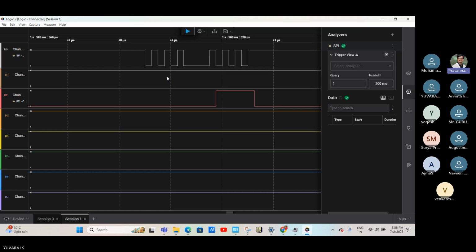Okay, but this is how we'll be transferring the data as well as receiving the data. Okay, if you have another board, you can connect this MOSI to MISO of that board and MISO to MOSI of this board. And apart from this, you just need to make one digital pin as a logical 0 for the slave select. Okay, so make that as a slave select, and then you can able to communicate with the multiple devices. Yes, so that is possible. Now that is for measuring the width.